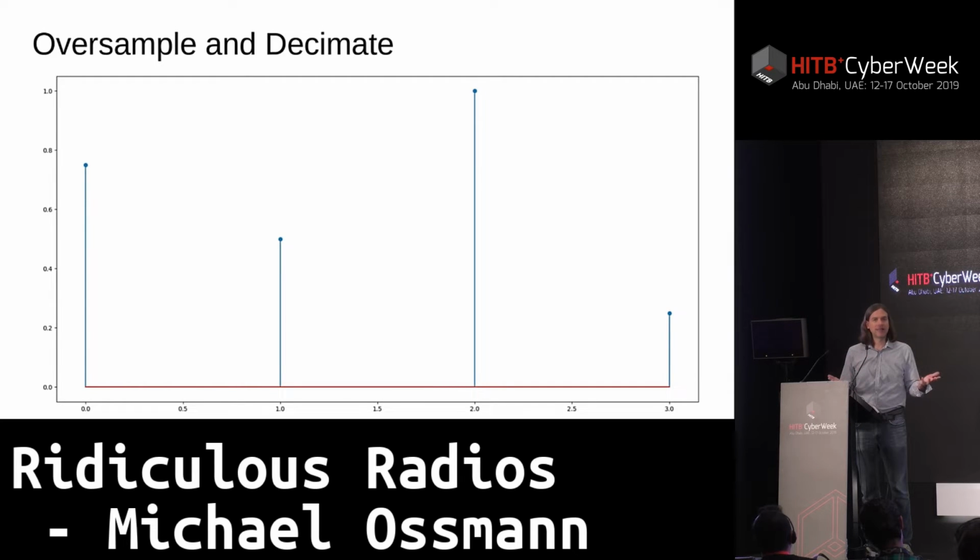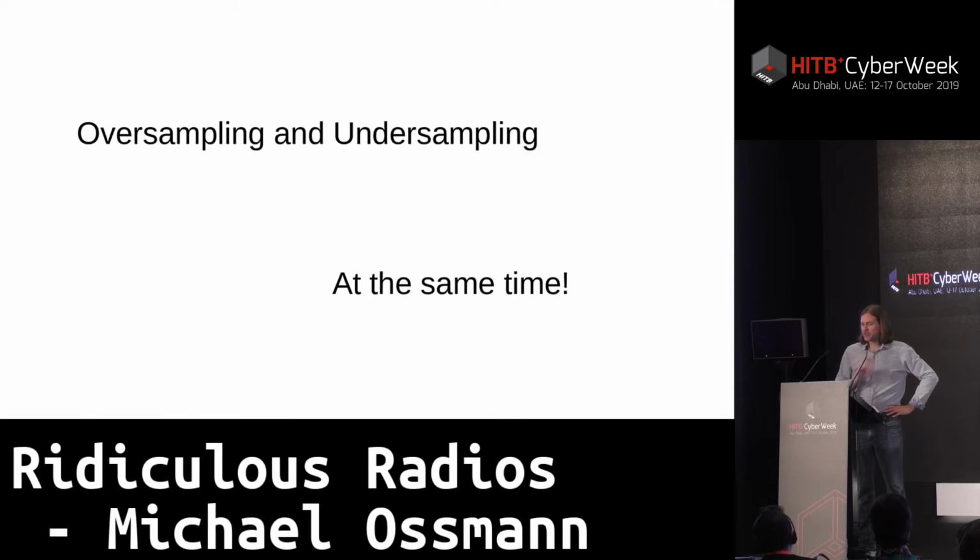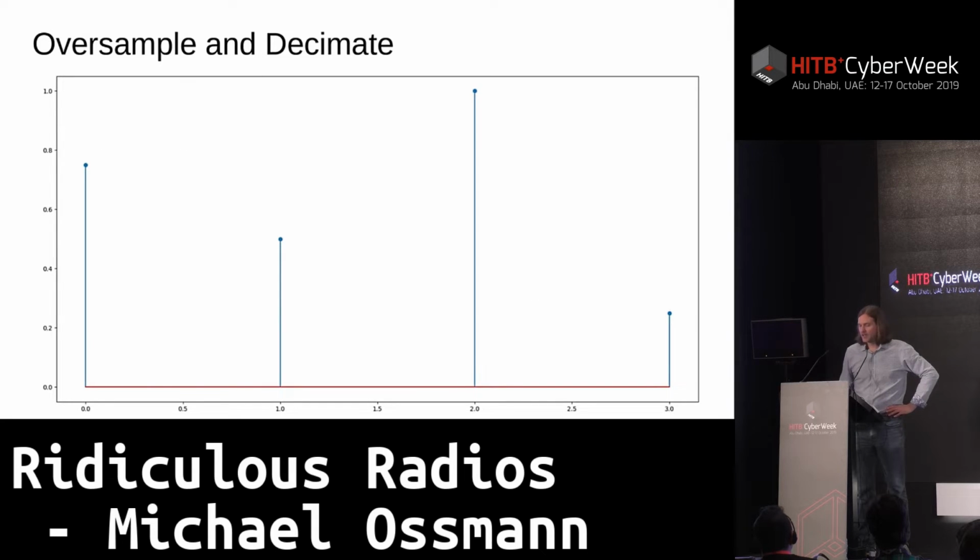You need 9 bits to represent all the possible results of that addition of 2 8-bit numbers. And the same thing we're seeing here. When we add 2 samples together, we increase our dynamic range, or we increase the number of bits per sample. We can continue this. Sorry, I don't have continued slides.